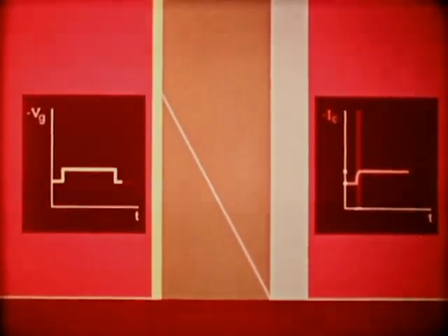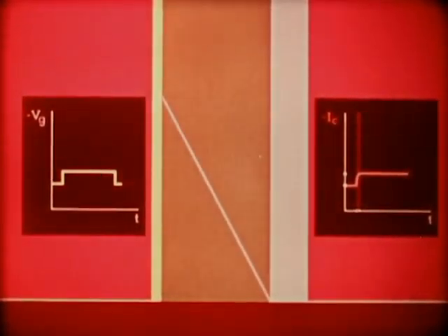What happened at this trailing edge of the pulse? The width of the emitter-base barrier region increased, and the concentration of the holes near the junction followed this change immediately, after which the concentration curve straightened out again.